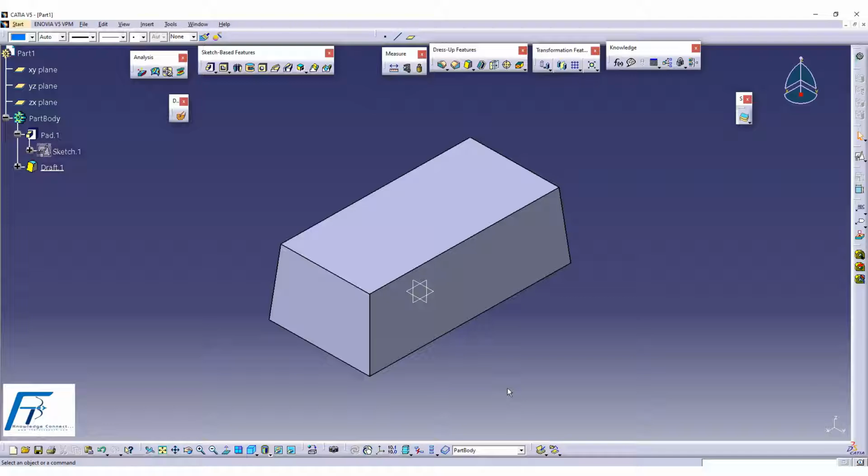So that means most of the time, maximum it could be 5 degrees. Or else, as Anku is telling, it could be 3 degrees for a plastic component. Metal casting could be different. Now, I'm going to give you a little idea about the operation and the feature which you are going to use.